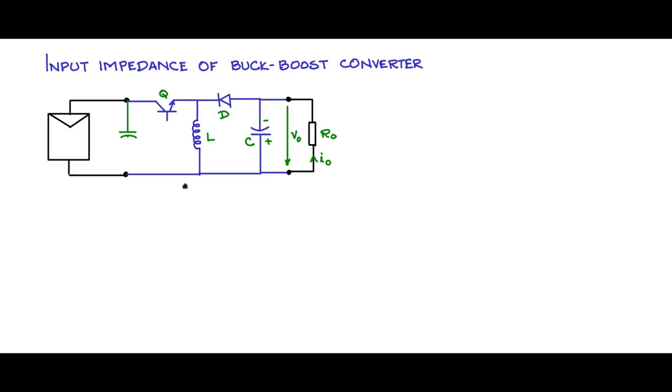like in the buck converter, connecting a capacitance CT like this is mandatory, because of the switch present here on the input line. The current through this is switched. The current is not continuous, and therefore the current through the PV panel also would not be continuous if you do not put the capacitor.